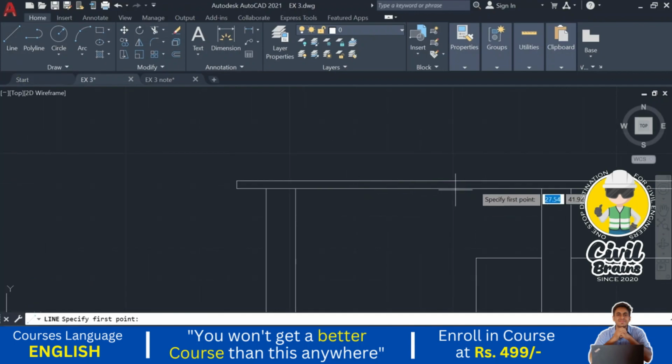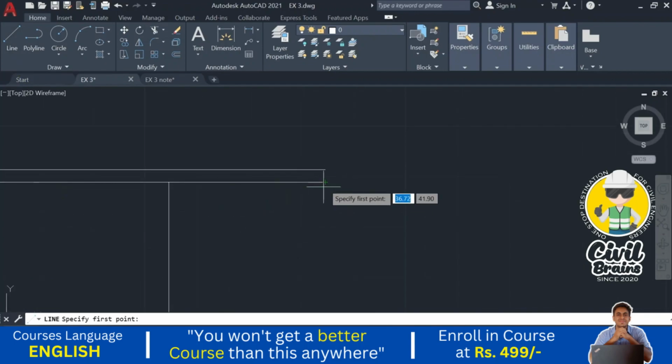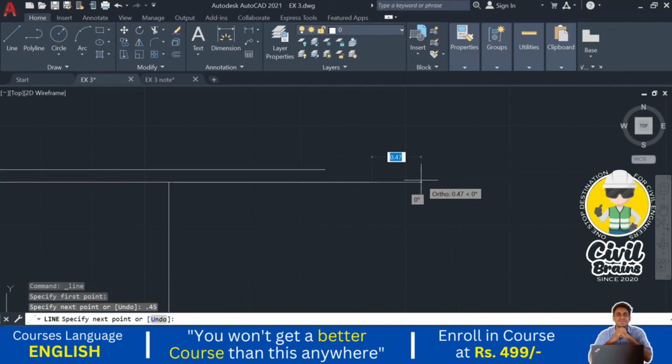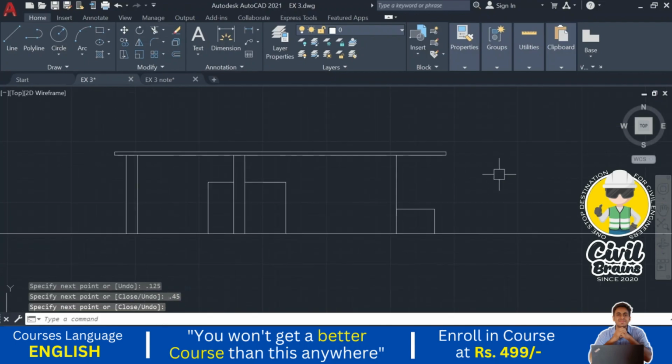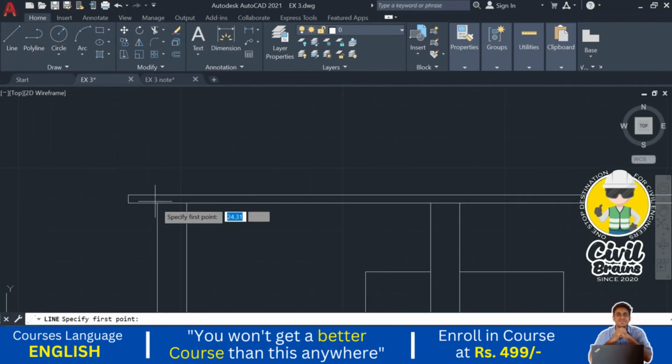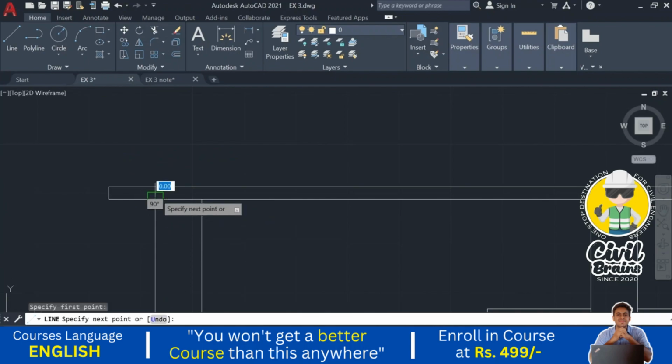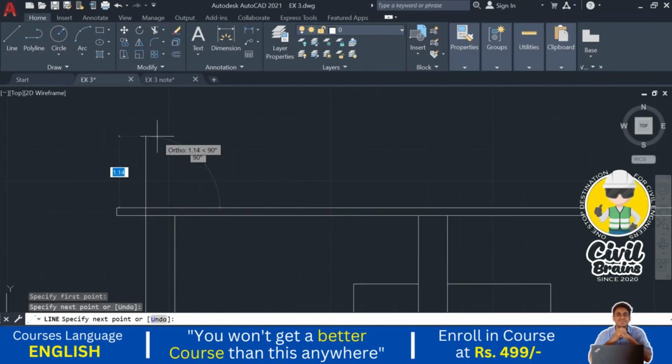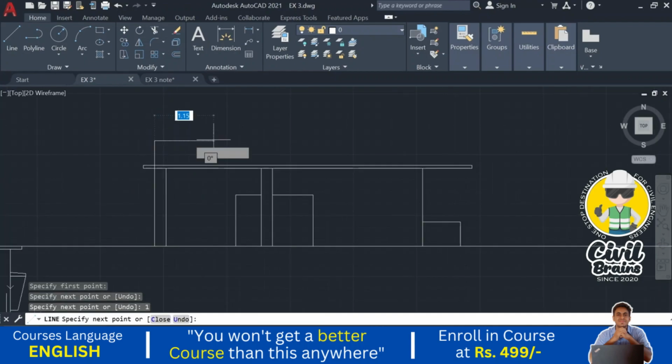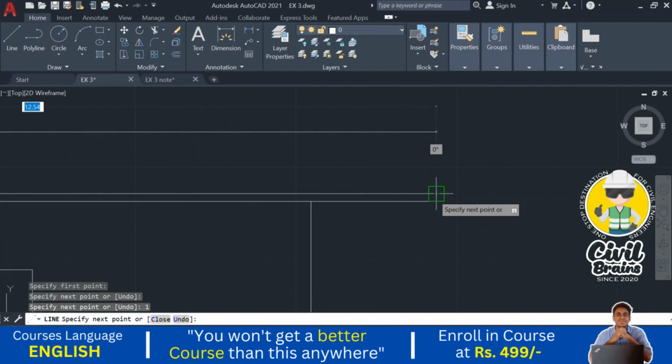Again I go here, 0.45, press enter, 0.125, press enter, 0.45. Okay, above the slab there is a parapet. I'm considering the parapet from this wall level, and the height of the parapet I'm considering 1 meter. Again press enter, and it is already provided as 1 meter only.